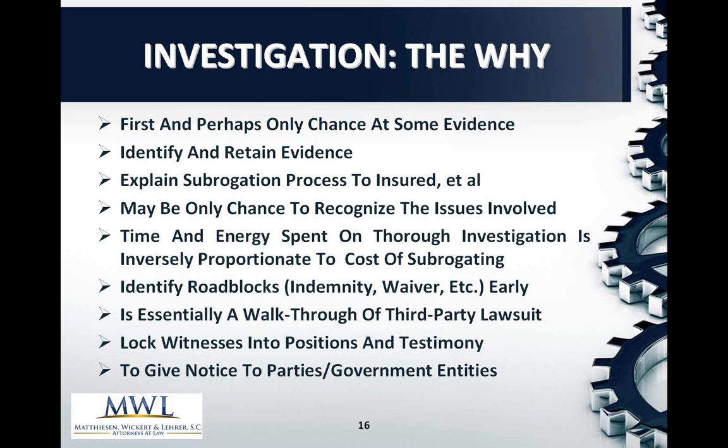And as I've kind of spoken to the why, it might be your only chance at the evidence. The repair company is going to come in, they're going to clean up the place, they're going to throw out essentially everything else that is wrecked or ruined. You may miss that piece of pipe that has a pinhole in it. You may miss that supply line where all of a sudden the coupling nut has broken. So identify, retain your evidence.